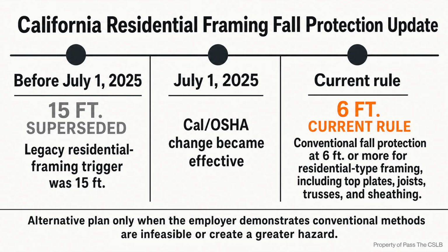I want the full lesson reduced to a few connected decisions. First, trace an unbroken load path from diaphragm to wall to foundation. Second, keep prescriptive braced wall placement separate from engineered shear wall details. Third, require solid backing at every panel edge and reject staples for wood structural panel shear wall and diaphragm fastening.